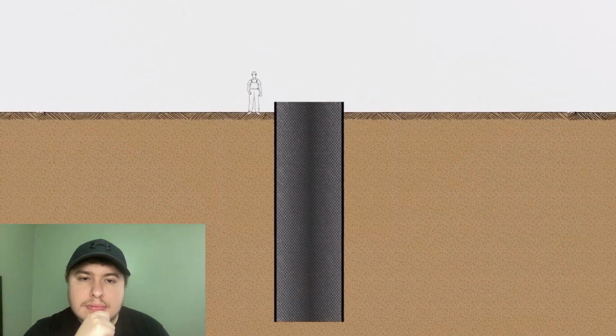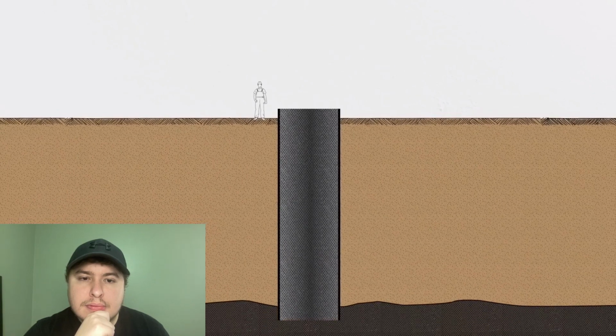Caissons can also be driven deeper into the subsurface, creating a condition similar to a cutoff wall on a dam. They can even go deep enough to reach an impermeable layer, creating a better seal that prevents water from flowing in through the bottom. Thankfully for that worker in BC, his colleagues were able to rescue him before he was consumed by the earth. Next time you see a dam, retaining wall, caisson, or any other subsurface construction, there's a good chance that engineers have had to consider how groundwater will affect the stability.